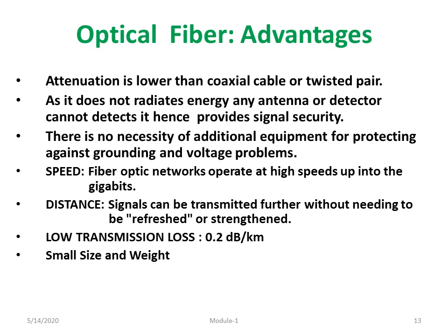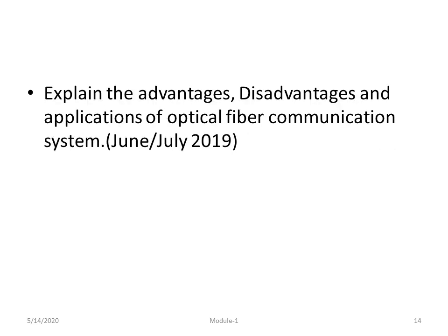Low transmission loss, around 0.2 dB per kilometer, and it is also made up of very thin, hair-size glass fibers, so the weight as well as the size is very small compared to coaxial cable or copper. So it can be placed easily in ships and aircraft for transmitting the data. So very small size and low weight.